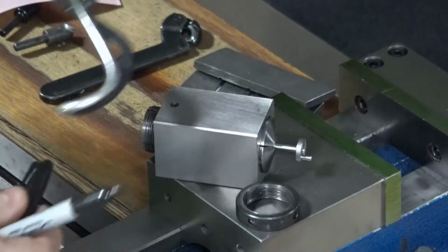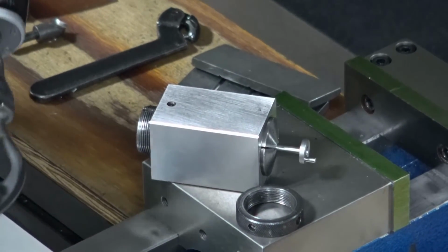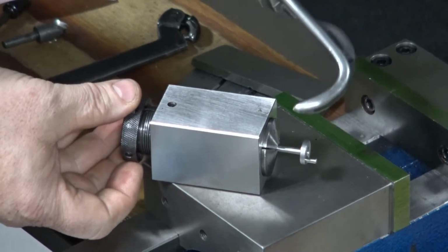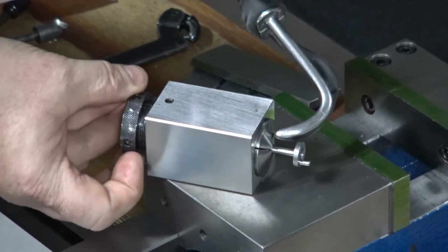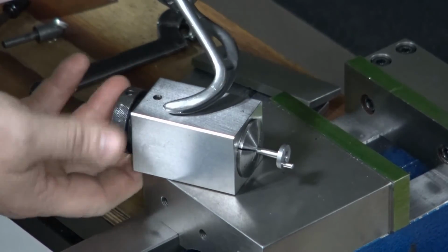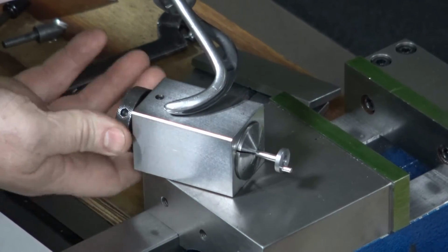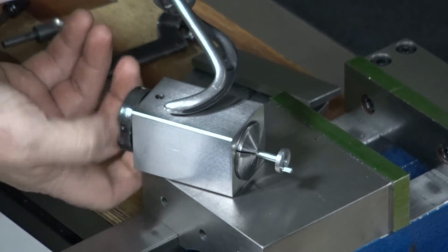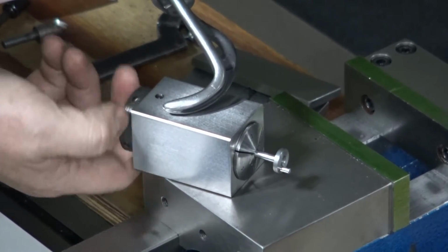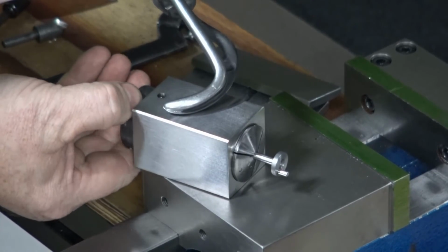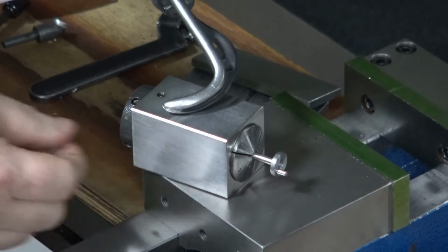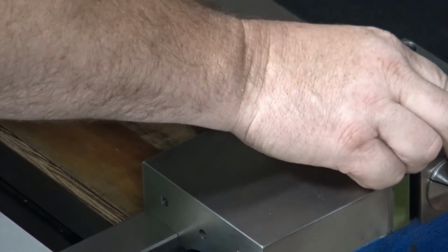So let's go ahead and get our collet block set up. Nothing on the drawing tells me that I have to have the flat in any orientation from where the pin is, but I'm going to position it in such a way that the pin's not going to get in my way when I try to do that touch off, okay? So right now, I'm at a position where I can still move that. I'm going to put it in the vise.